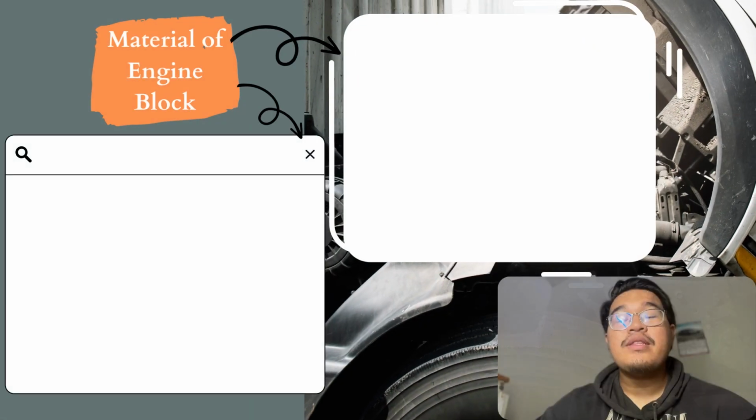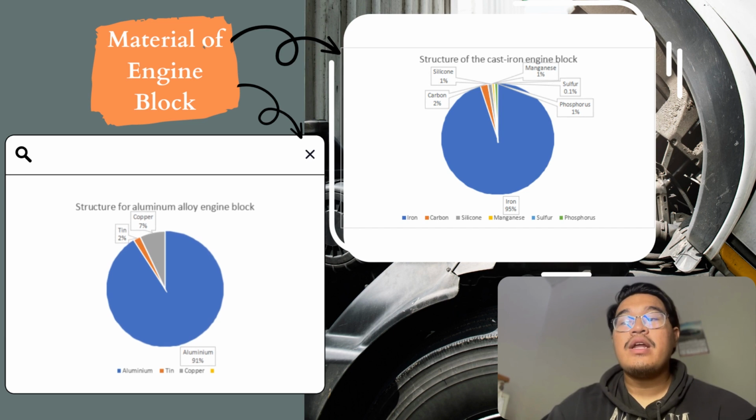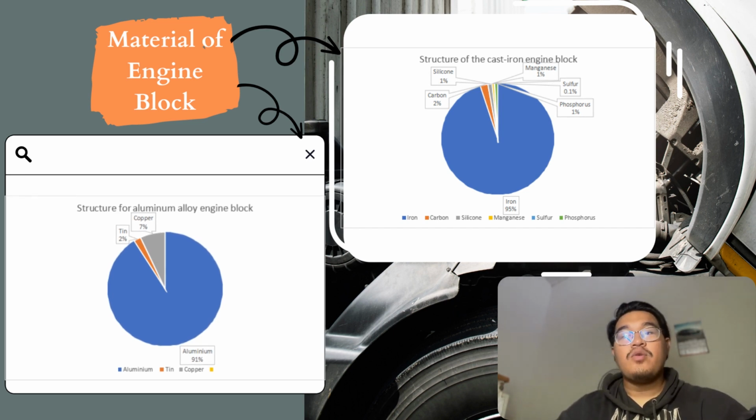Then, the material of the engine blocks. Manufacturers use grey cast iron and aluminium for engine blocks. Nickel and chromium boost their characteristics. Cast iron reduces abrasion in most engine cylinder walls. Plating cylinder walls with chromium reduces abrasion and extends service life.